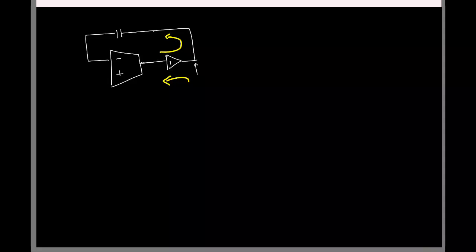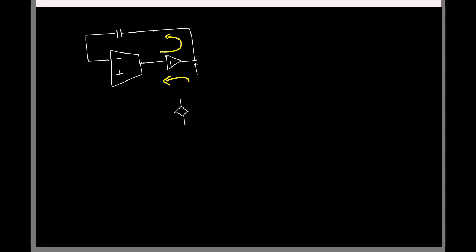See, the buffer is a voltage source, a voltage controlled voltage source, right? An ideal voltage source can provide or sink any amount of current. This is the connection we are making. It will not be able to take the current from the VCVS, right? That is okay. We don't want that.